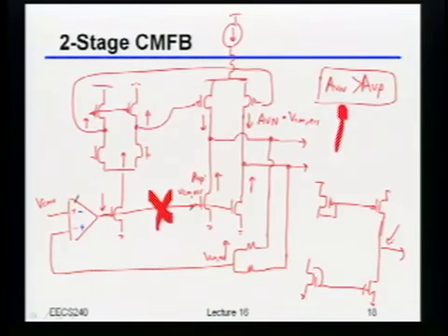Or? This is saying that the first stage's common mode affects the second stage's common mode. Yeah, it's true that, the way I drew it before without this current source on the top, it does affect it, right? But if I didn't have any feedback onto this point, there's no reason why when I control this common mode, I'll get exactly the same common mode over there, right? Because again, the ROs are a little bit different. The mirroring ratio could be slightly off, right? And if I have a gain of, let's say, 100 through here, all it takes is 10-ish millivolts or so, and I'm out of the rail, right?